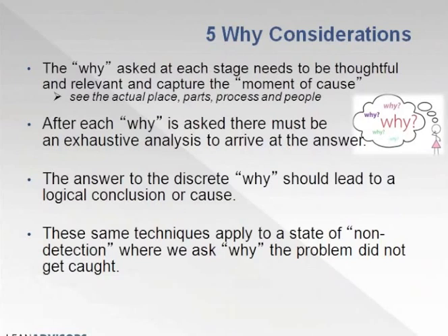But here's the point we're trying to make. The machine tells the maintenance department when to clean the filter. There's a little green light on the machine that blinks and says, filter clean required. That's being ignored. Instead, this organization is spending $800 every time they blow a bulb out to replace it. So we want to look at that from the standpoint of we've uncovered the root cause.